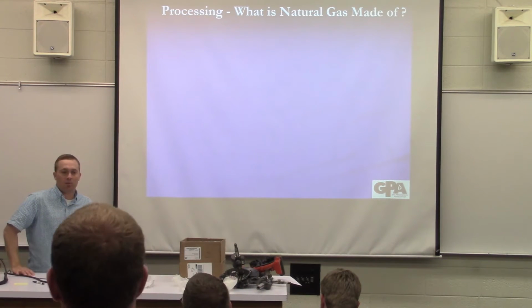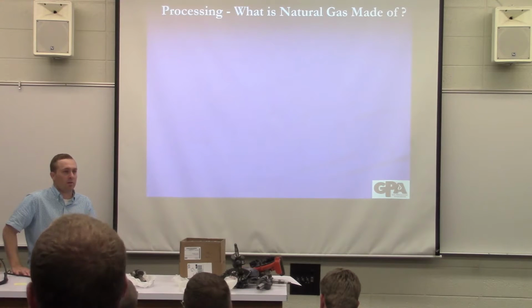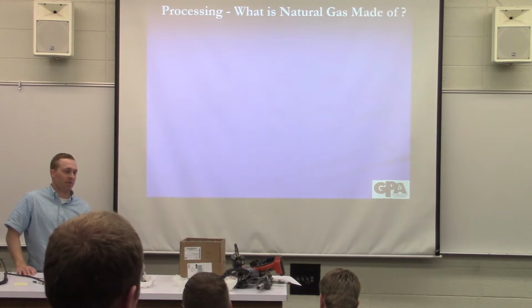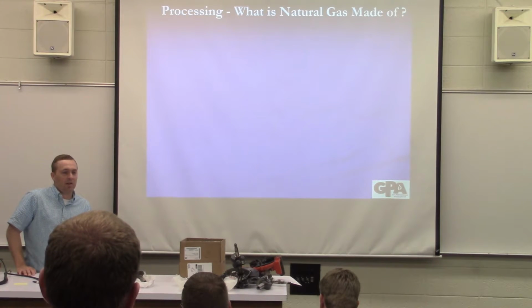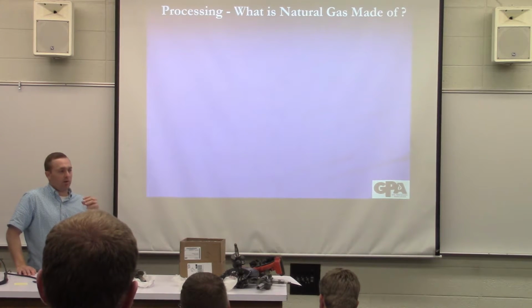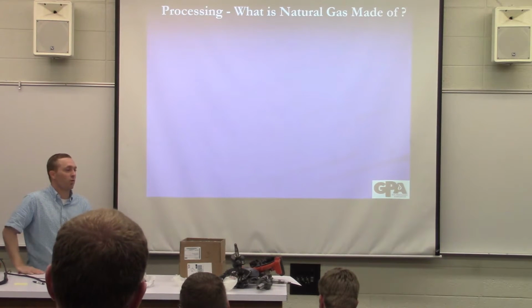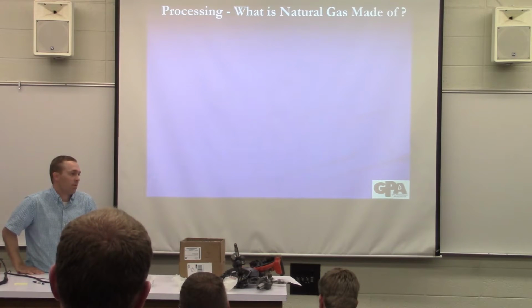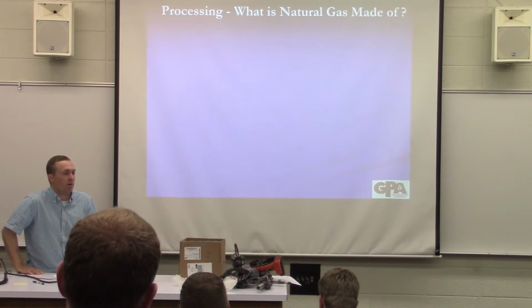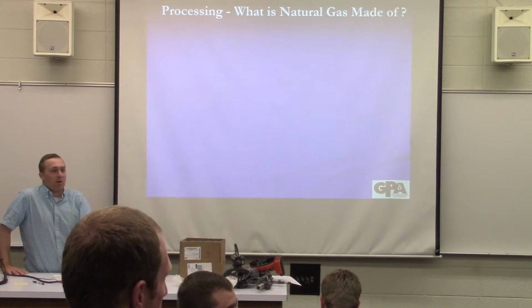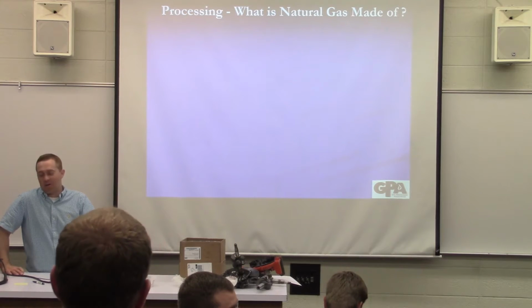and I'll get into more of the types of processing facilities that we have, but there are some natural limitations, and I've seen where we operate close to that freeze point, and even to where we start to see high differential pressures at the top of our tower, where we think, okay, we're forming dry ice, we're freezing carbon dioxide in our equipment. Right? So Dr. Baxter, you probably have a more technical answer about that would involve the word azeotropes. Perfect answer. Okay.